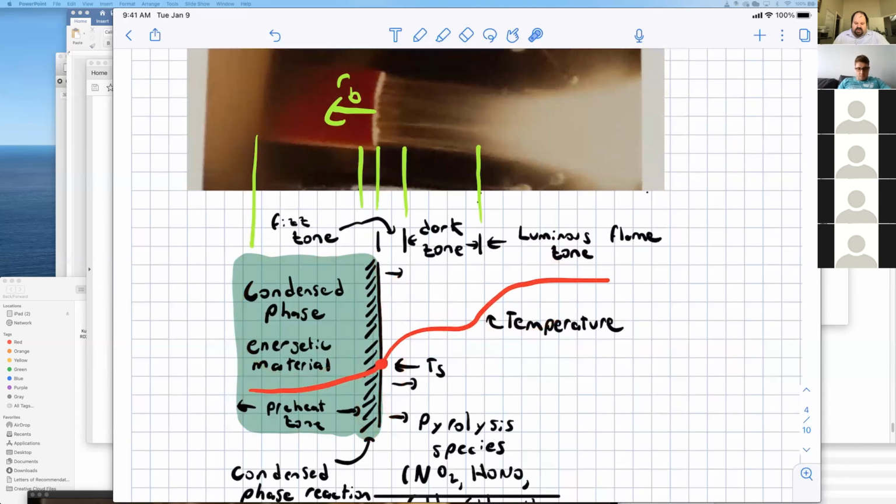And so, all put together, the temperature profile starts at some temperature T0 here and goes up to the surface temperature, where the gas phase and condensed phase temperatures have to be the same. There will be an initial little bump up in temperature due to some rapid reactions occurring in the fizz zone. Then they'll taper off and achieve a metastable state.